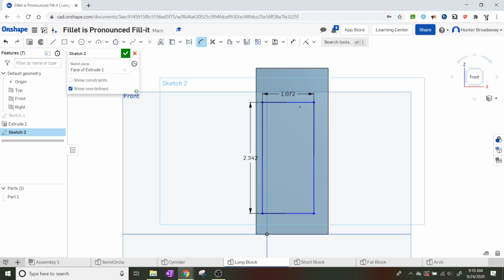And how you actually make a fillet work in a sketch is you click one side and then you click the side that's right next to it and it will round off the corner. And if you need to do it to multiple sides, you can continue doing that all in one operation. So if I want to round off all 4 of these sides, I can just keep clicking around on the sides. Let's see here.